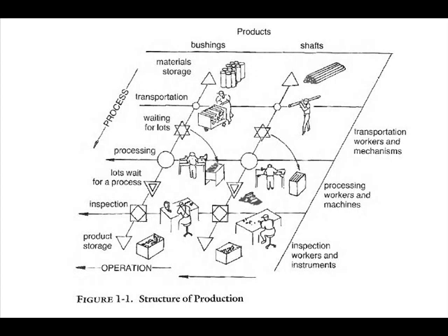Chapter 5 takes a closer look at improvements in internal setup operations, stressing three areas of improvement: the implementation of parallel operations, the use of functional clamps, and the elimination of adjustments. Chapter 6 describes the application of the SMED system to metal presses and plastic forming machines. Three types of metal presses are discussed: single-shot presses, progressive die presses, and transfer die presses.